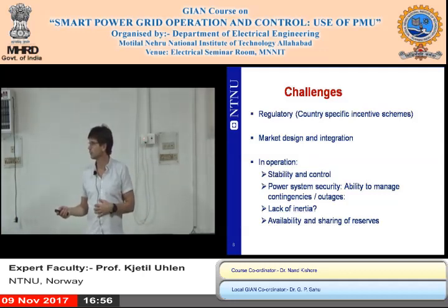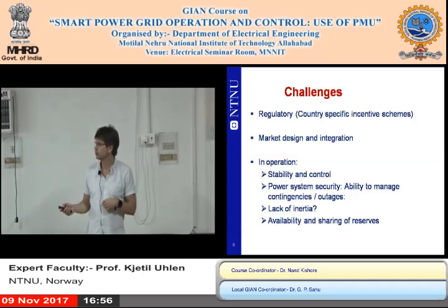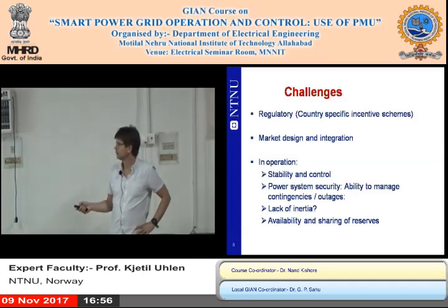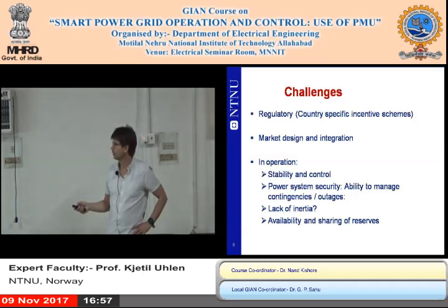So you can make a control scheme so that you control the voltage as a function of the active power in and out of the DC grid. So if all the converters are equipped with such a voltage droop scheme, they will add up to a total aggregate scheme where the operating point would be around here.